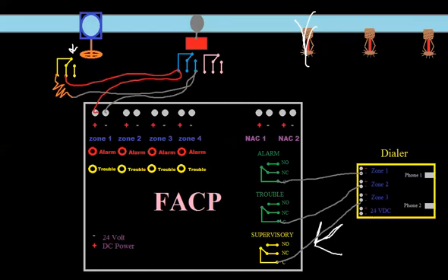So now that we have another signal, we need to have a way to send it, and I can go in and program this dialer and tell it that zone 3 is supervisory, so when it sends it to the dispatch center, they'll know that if one of these valves is shut, or sometimes duct detectors are programmed for supervisory. So I think that's pretty straightforward.